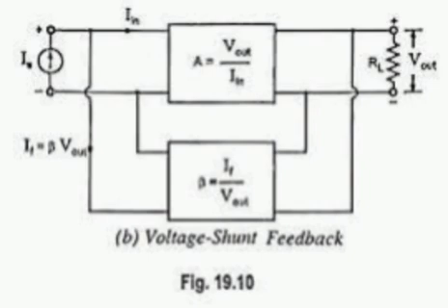Operational amplifier, differential amplifier. Vout equals A times (V1 minus V2). Two common emitter resistances, with RE common at the bottom and RC going to VCC at the top. Vout means the voltage between the collectors. A means capital RC by small re, equal to gm RC. Small re tends to the emitter resistance.